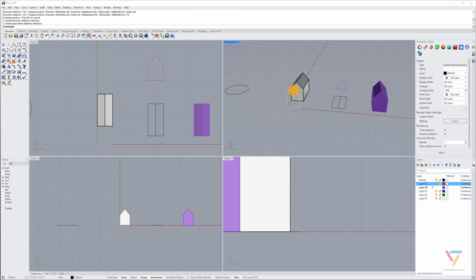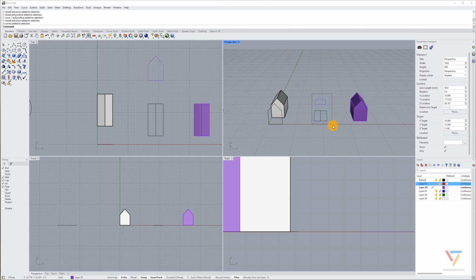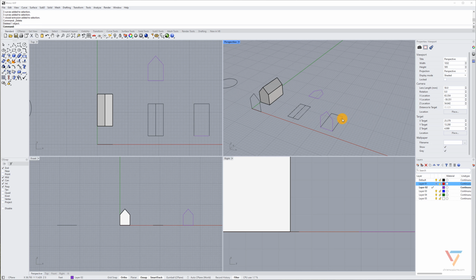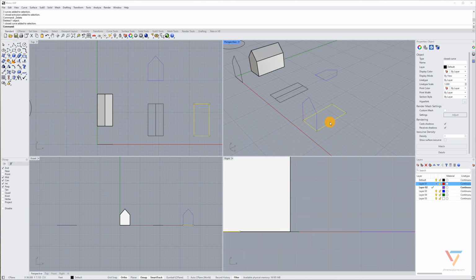Now, this was my original 3D geometry. This is my new geometry based on what I see here in my 2D drawing. There are a few other commands that we can look at right here, and those kind of go into how we might make further manipulations. We've looked at rotation and we've looked at moving. And those are both called transformations, geometric transformations. There are other ones that we can look at as well. If we wanted to make this house not 10 feet deep, but maybe 20 feet deep, we could scale this rectangle.